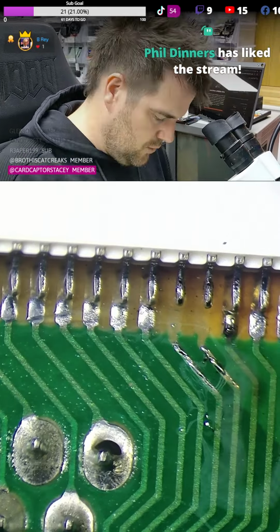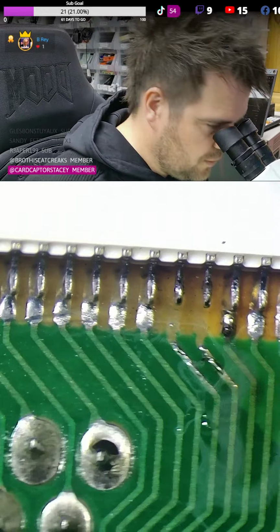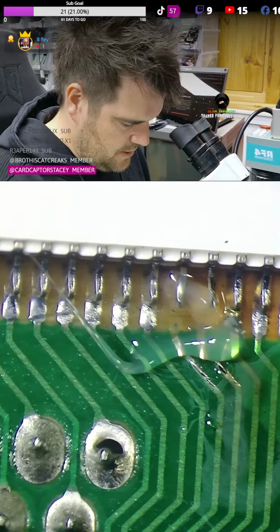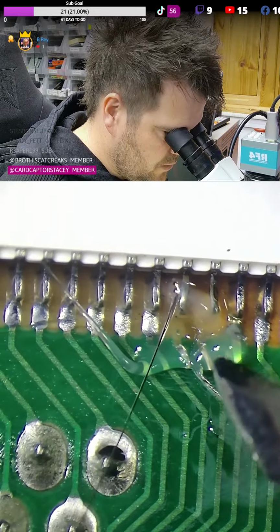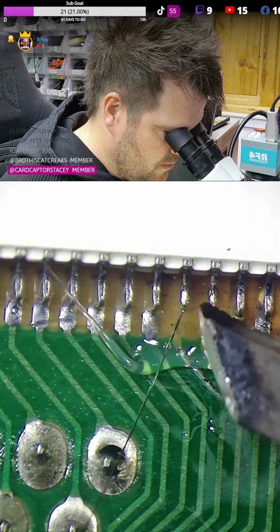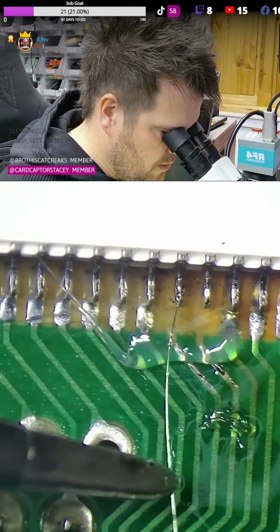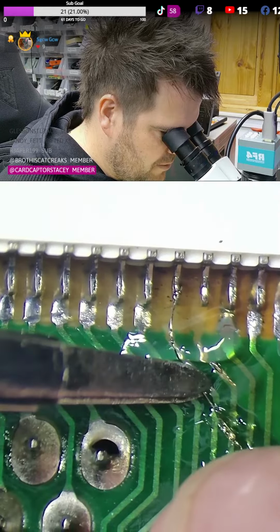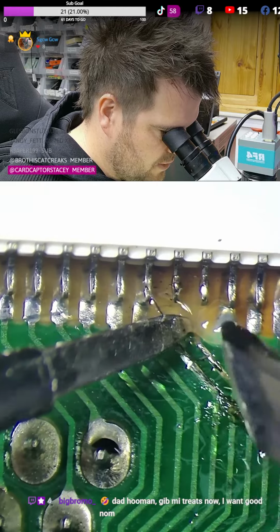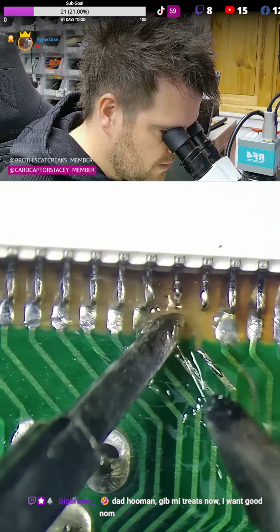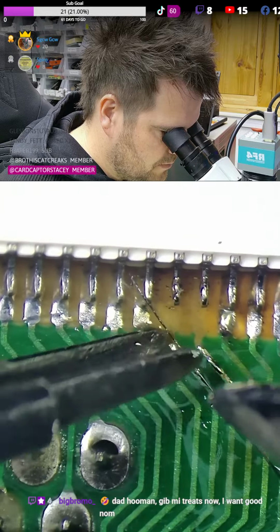So now with this wire, all we should need to do is, there's enough solder on the board. You should just have to put flux back on here and here, and then get your super fine wire, so you can see how you can barely see it. We'll tack it onto, say, the pin first, like so. Get tweezers, come down, and we will get this lined up, say roughly. It's come off the other pin, but let's ignore that. Tack it down to the trace. Send that back onto the pin.